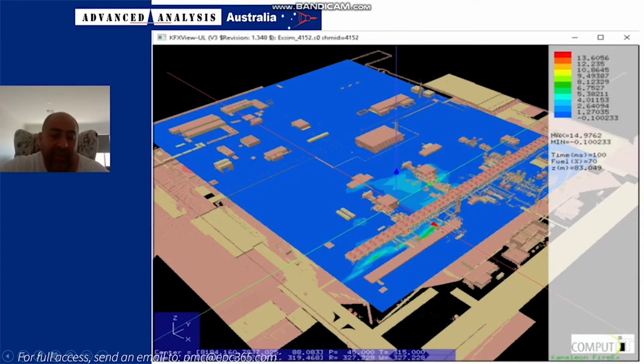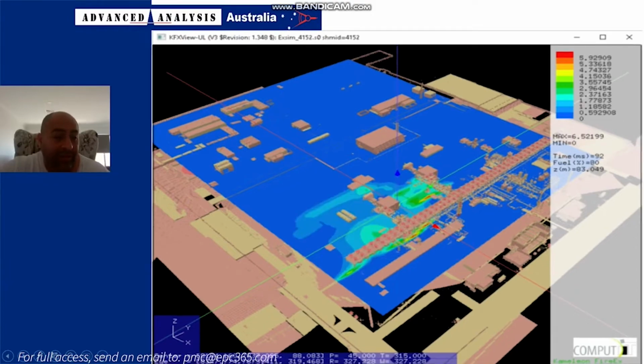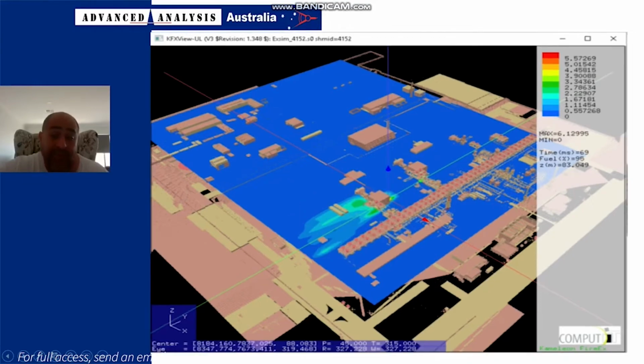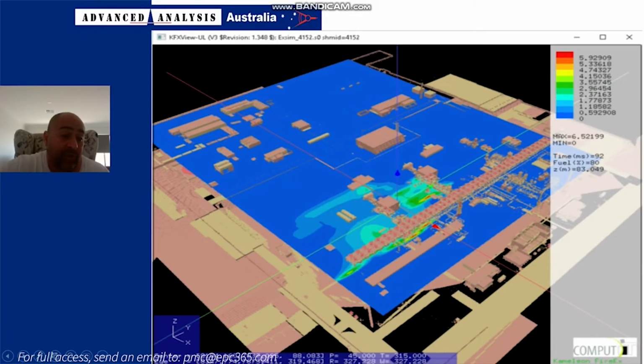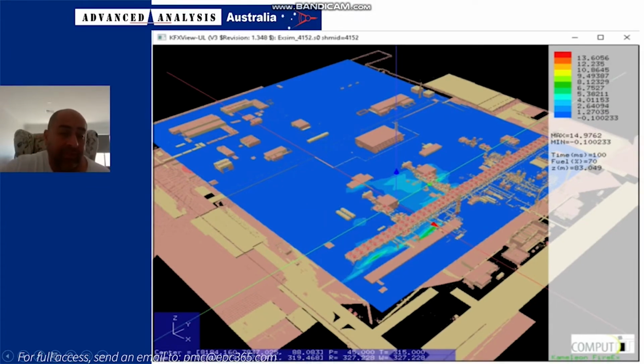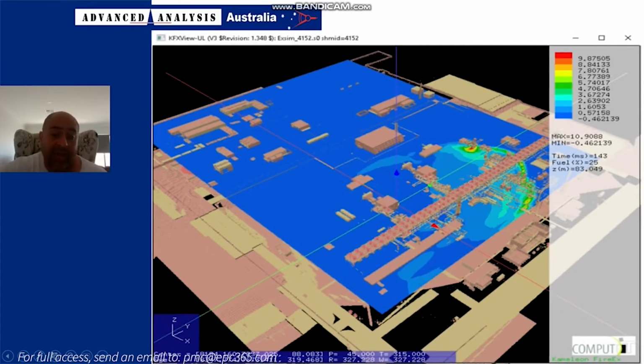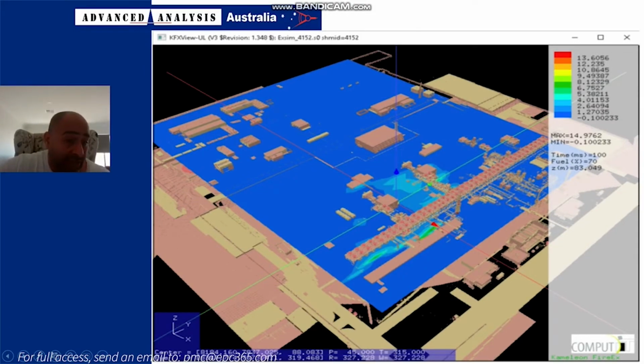This is something that we don't discuss too often, but there's a 30-50%, even order of magnitude sometimes, uncertainty for state-of-the-art CFD. So it pays to be conservative and to try and stay within the limits of the uncertainties of 3D CFD. And that's the approach that we've taken to model this.